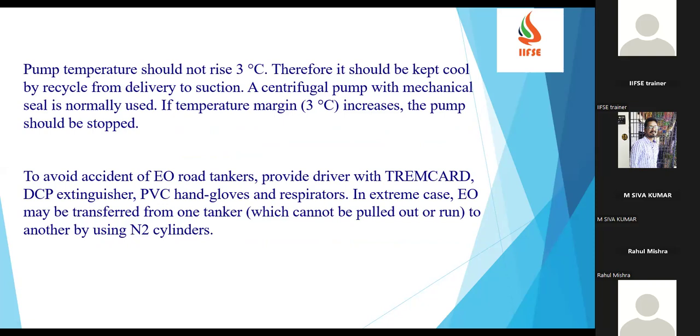Then the pump temperature should not rise by more than 3 degrees centigrade. Therefore, it should be kept cool, and also recycled from delivery to the suction. A centrifugal pump with a mechanical seal is normally used. If the temperature margin of 3 degrees is exceeded, the pump should be stopped. This is also one of the safety controls.